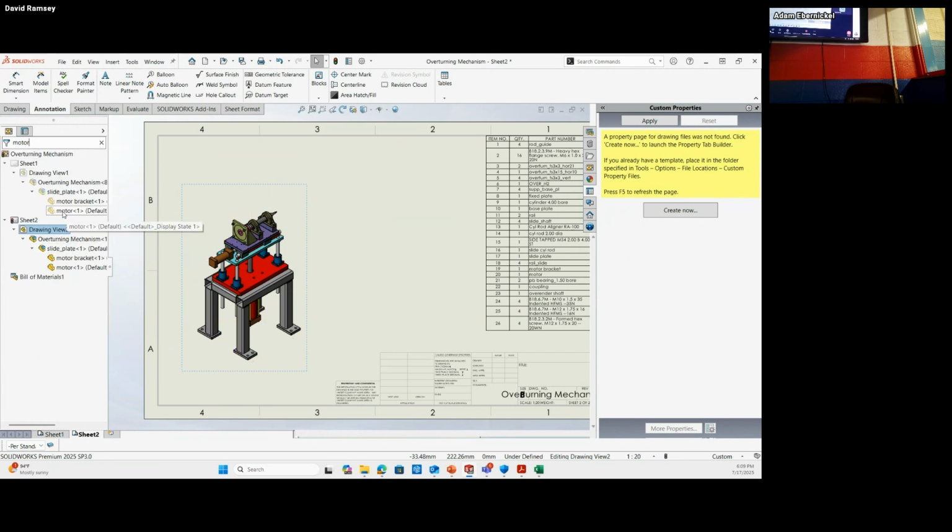Right, so there's a motor, and in this case you can see it's kind of ghosted out. But if I select it, so it's this one, sorry. If I select it, you can see the bounding box selects and it picks it in the bill of materials. So it's still physically there. Display states give us the ability to show things on a different level, but still have a lot of the fundamental function that we want here without a lot of the graphics load.